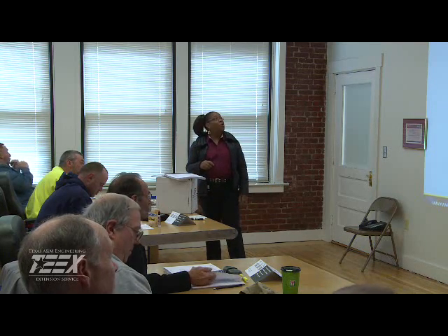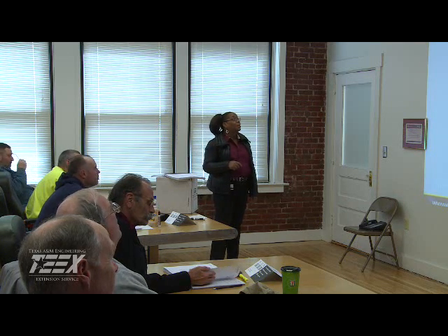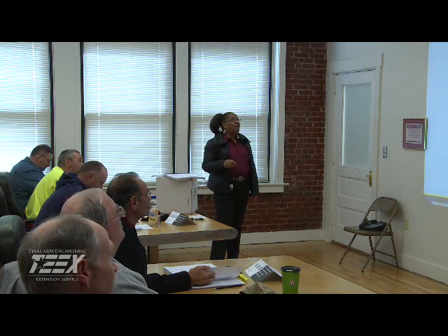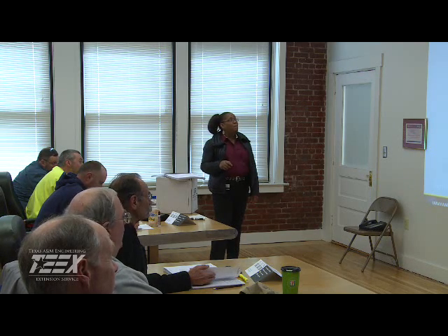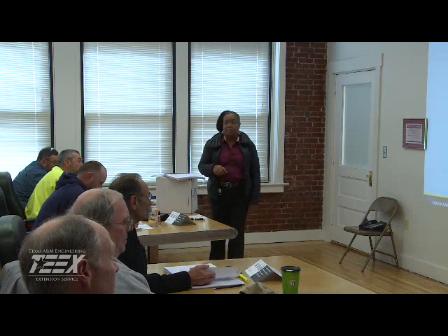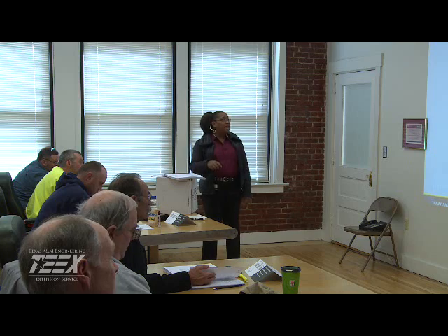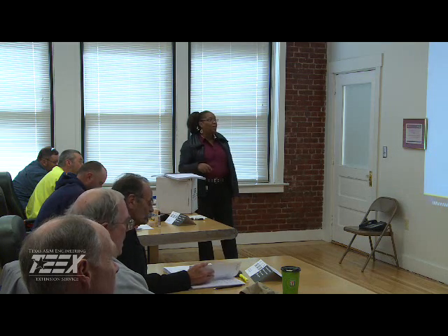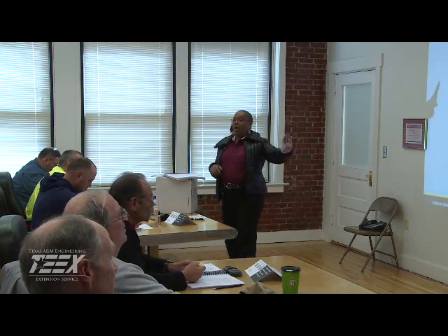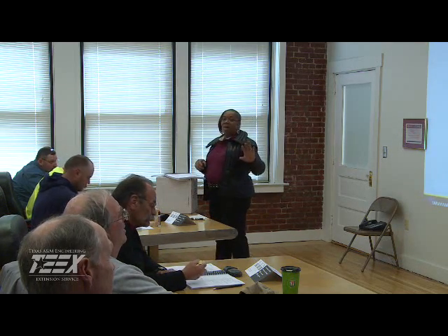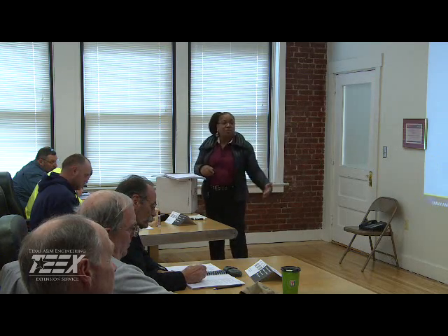All right, under the new changes, your public water system vulnerable to microbial contamination must identify and fix the problem. No longer a suggestion or proposed change. Must establish criteria for systems to qualify and to stay on reduced monitoring. In other words, if you've had a crystal clean bill of health over the last year or so, you have to continuously demonstrate and qualify to continue that quarterly sample as opposed to the monthly sample.